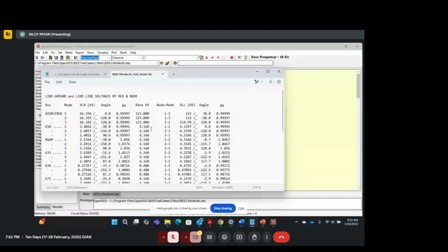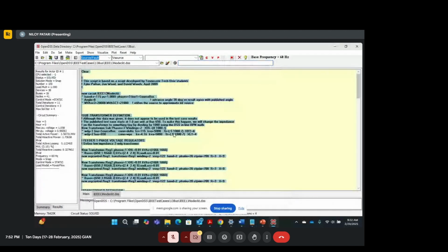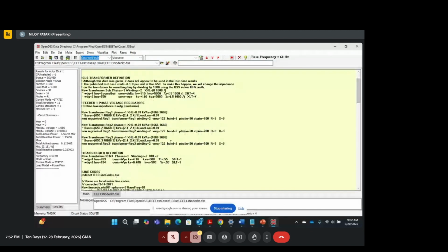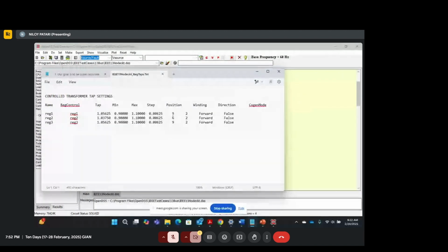And then you can check how the voltages look. Now the other thing is, if I show the taps now, I think the taps are still 9, 6, 9, right? Now, when the taps are at 969, what it actually means is, this is the position 9, and then you have this tap. So you have regulator 1, reg 1 node, how much is the voltage at reg 1?